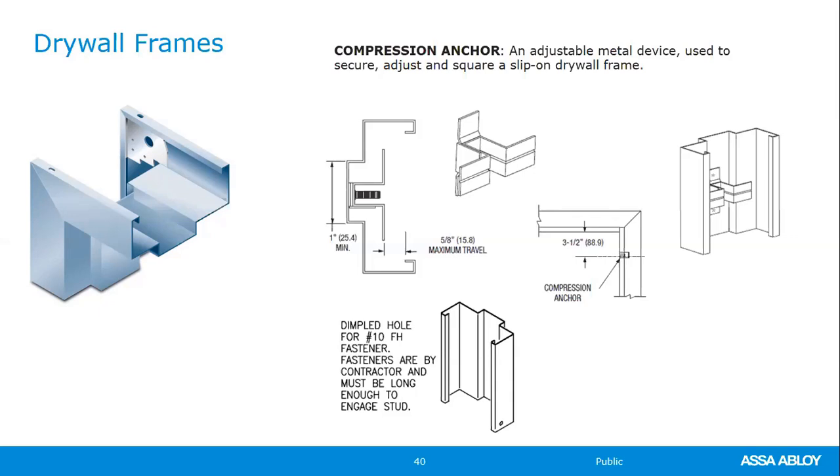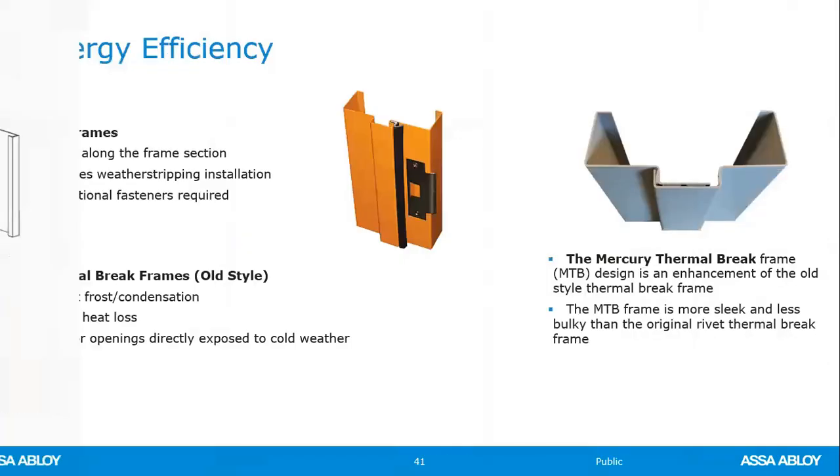Again, we didn't talk about this much, but this drywall frame can only be fire rated up to 1.5 hours. Masonry frames can be fire rated up to 3 hours. And both of them are provided that you have the proper anchors in that frame.